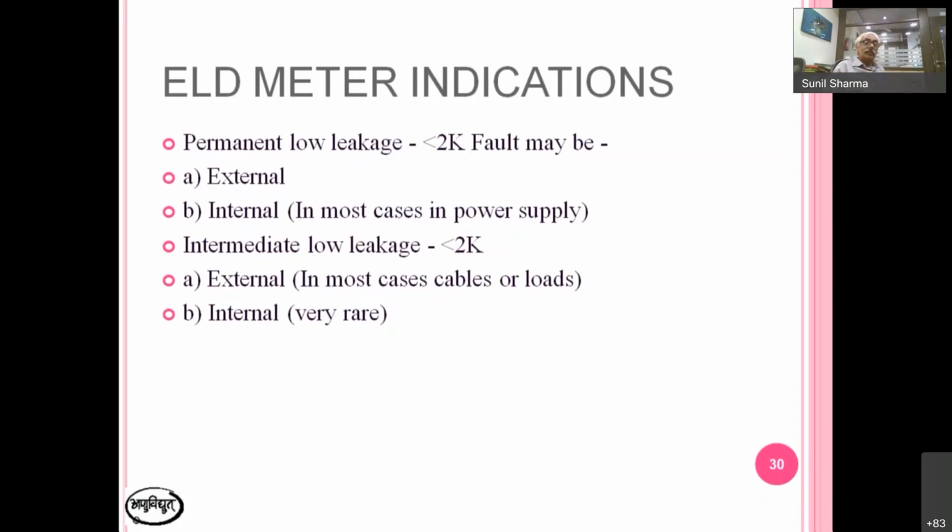It establishes a low insulation and becomes a leakage path with each battery, maybe more than 1 battery, 2 batteries, 4 batteries. So either insert your insulation pads below the battery or wash them. These are the only two methods. So you can improve this leakage condition and it becomes okay.